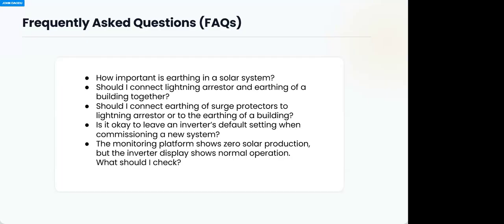It is your own remit to go and check and make sure that you follow the specification of the battery, and set the charging current accordingly. If not, you are going to blow up the battery by overcharging, because you'll be feeding the battery with 60 amps when the battery's recommended charging current is supposed to be 20 amps. There are so many other parameter settings like that you need to set.